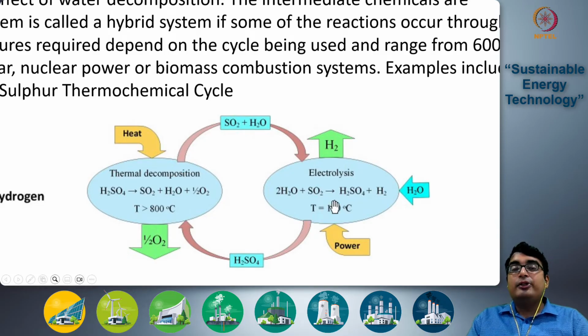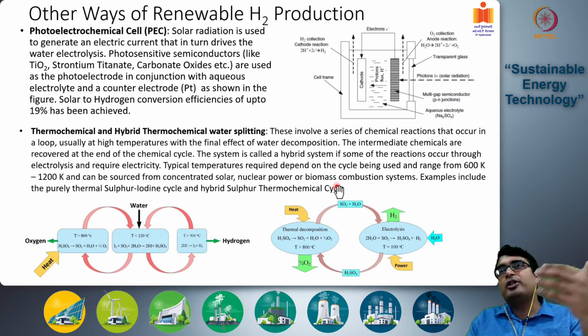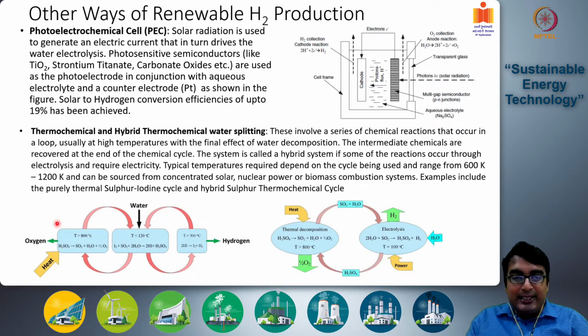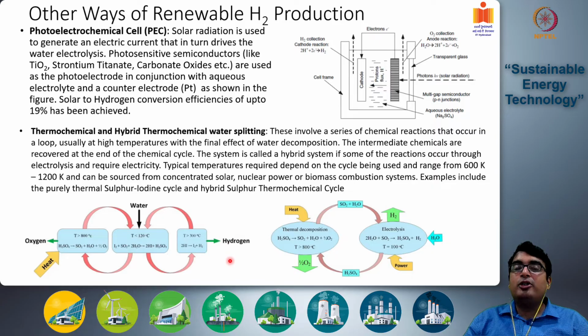Alright. So there are certain advantages and disadvantages of these methods. The first advantage is you can use thermal energy. Often there is a loss associated with converting thermal energy into electrical energy. So for example, in a concentrated solar power system, instead of using concentrated solar energy to generate electricity, you can use this type of system to use the temperature of the molten salts, which can be stored at 800 degrees centigrade and above, to generate hydrogen.